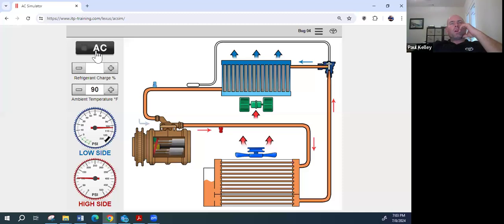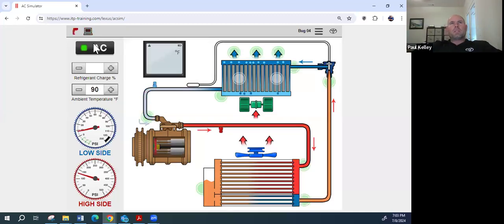All right, I walk up to the car. I can check the static, but a lot of times we'll actually power the AC on, bust out the temperature gauge, thermometer. Yeah, it's blowing 82, 80, 88, 90. That's pretty crappy. That one's not great. All right. Anybody want to go ahead and, now that you're understanding what we're doing, give me some advice on what we should check next?